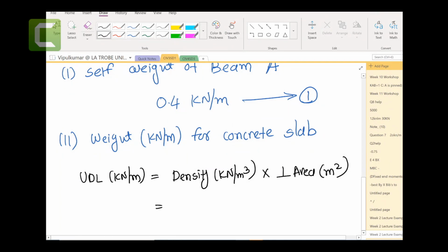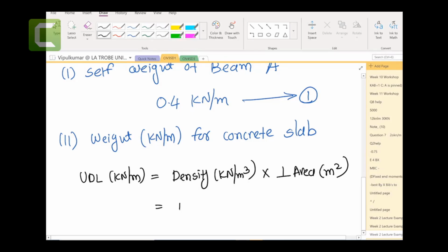Concrete is the most usable material in the world. Man-made material. You can see concrete around. If you are sitting at your home, you will see concrete. You will not find a place with man-made structures where you will not find concrete. So we must know a few of them by heart. We don't need to remember, but by practice. So what do you think? This is here, table A1. Reinforced concrete. Slabs are generally made with reinforcement. It's not always, but mostly we need to put reinforcement in concrete. So 24 plus 0.6, 24.6. That we can make it 24.6 kilonewton per meter cube.